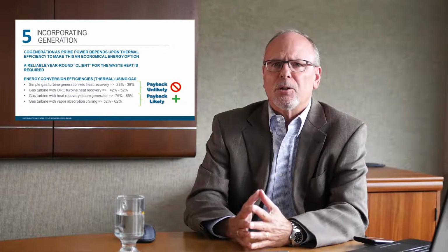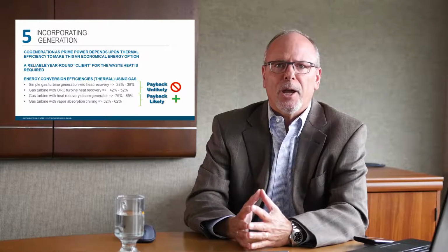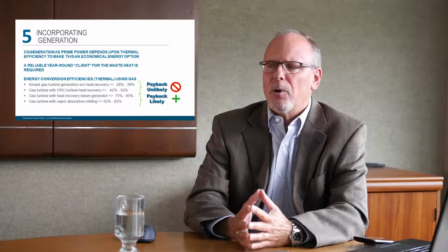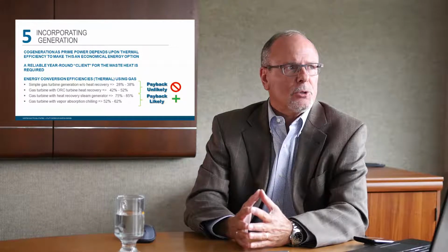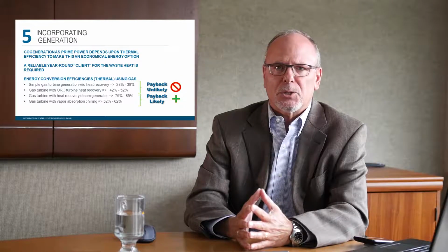If we look at our energy conversion efficiencies, this really shows the picture for payback using generation. A simple gas turbine generator with no heat recovery, where we just simply eject the waste heat up the stack, is somewhere between 28 and 38% efficient. What this means is that the gas you put in the front end, the energy contained in that gas, we only get about 28 to 38% of that energy back in the electricity that's generated. Pretty low efficiency system. Pretty good for peak shaving though.